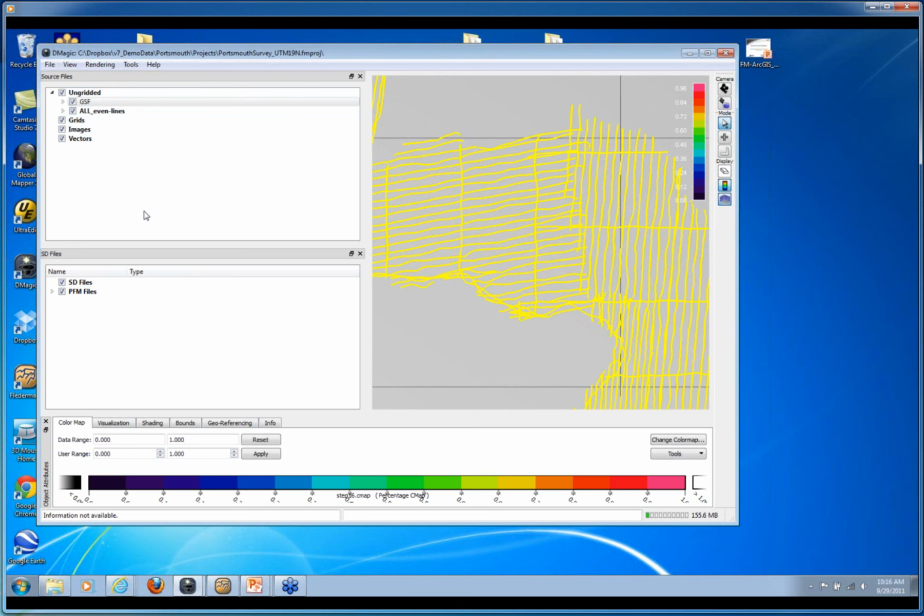The next step in the hydrographic workflow is to create what's called a PFM object. Our PFM object is what we use for editing multibeam data. So it creates a series of surfaces that you can, from the surface, access the soundings, clean out rogue soundings. You can also create a cube surface, and you can validate the cube surface, and from that you can generate clean soundings, a bag product, selected soundings, etc.